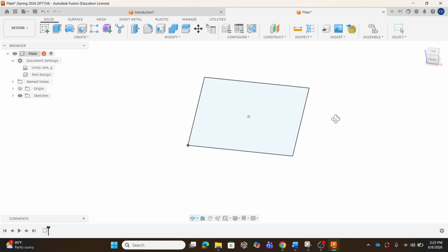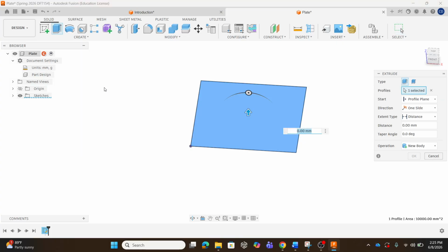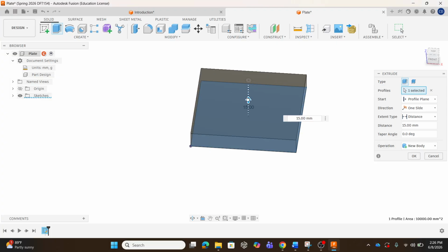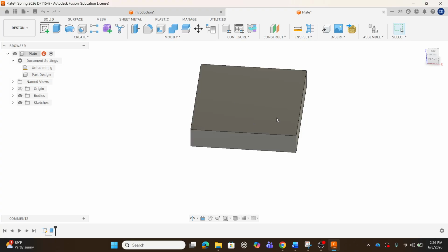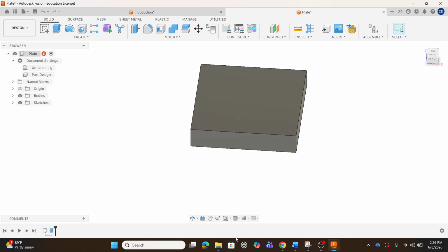and then I'm going to twist it just so you can see. We're going to come back up here to the top left. Notice my Extrude button. Click Extrude, and then I'm going to drag it up and type in 20. And notice how much faster we made that object the second time. It's the exact same one we saw from the first image, but I drew it a lot faster. That's where the shortcuts come in with drawing squares and circles and things like that. So those are two methods that you can use.